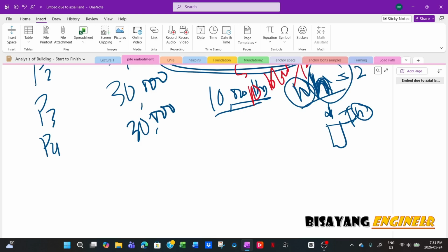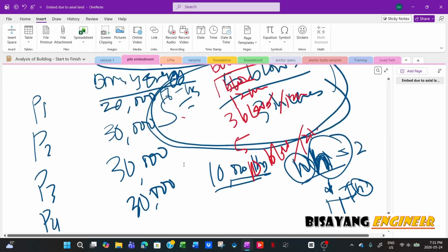So if you use the same criteria for more than 2,000 piles, then imagine how much it will cost you. But if you at least group the piles and then determine the actual blow counts required, the number of blows, then you can save a lot of money.